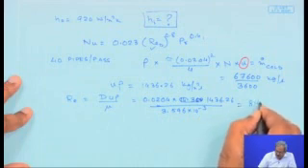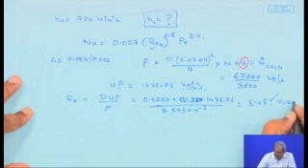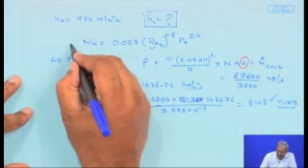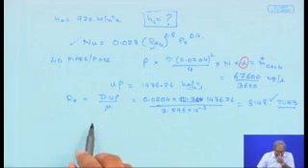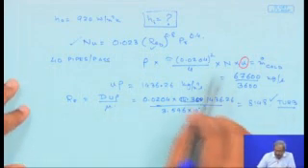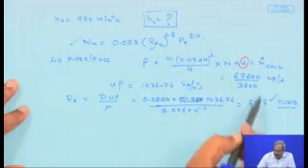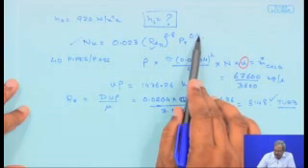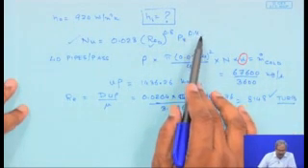So, 8148. Therefore, this is definitely in the turbulent range, and since it is in the turbulent range, the Dittus-Boelter equation can be used, and it's a problem of heating. So that's why the Prandtl number, heating of the cold tube side fluid, has the exponent equal to 0.4, otherwise it should be equal to 0.3.